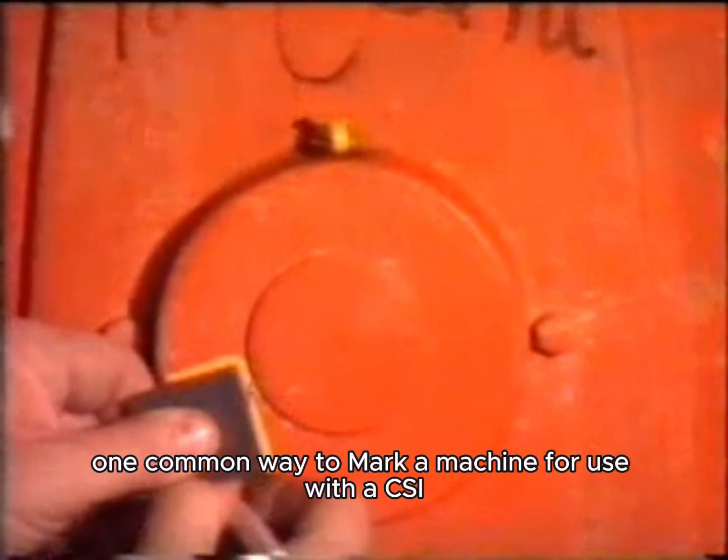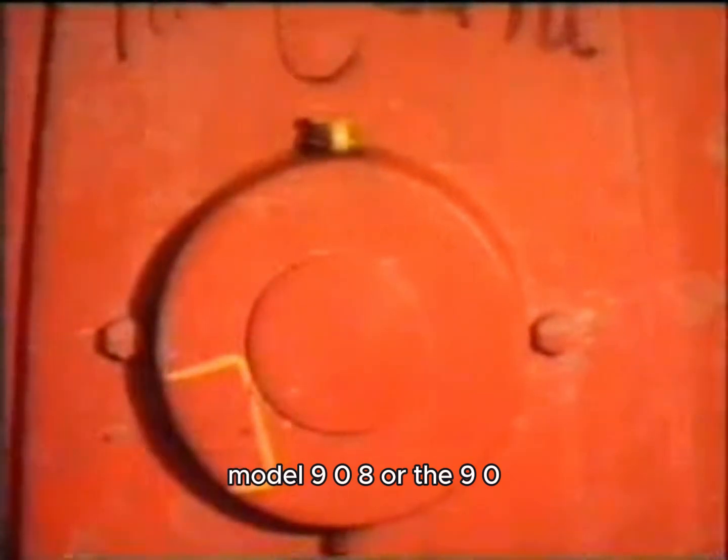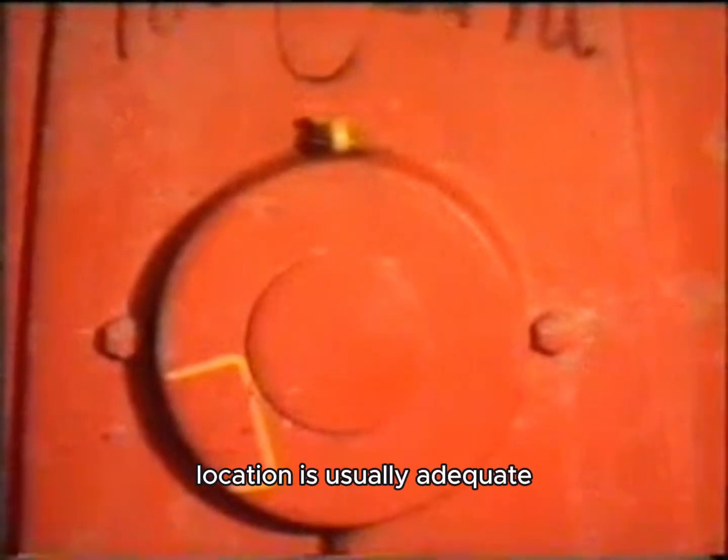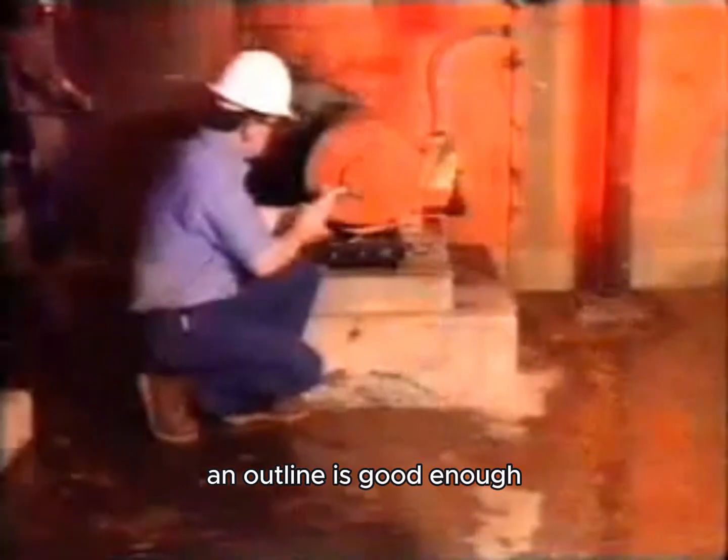One common way to mark a machine for use with the CSI Model 908 or the 906 two-pole magnets is to use a paint marker to draw a target. A single line around the perimeter of the magnet location is usually adequate. It's not necessary to paint the target area solid. An outline is good enough.